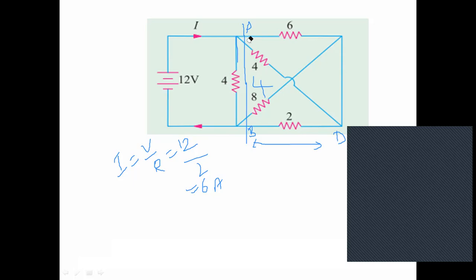Okay, you understand now? So the right side of this part is the same as we solved previously. We obtained a 4 ohms resistance. Another 4 ohms resistance is connected in parallel with these two terminals. So that's why the 4 ohms combination produces 2 ohms. So the total resistance is 2 ohms. Then I is equal to V by R. 12 by 2 gives 6 amperes of current, to find the current I.